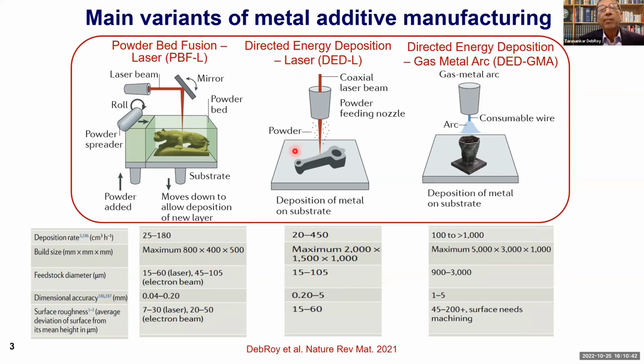We also have another technique that we call directed energy deposition using a laser beam. Here the powders are fed coaxial with the laser beam, and a computer guides the passage of this beam and the interaction between this beam and the material. Particularly, it melts the powder while it is being deposited, as well as on the part itself. And eventually, we do many layers of deposition, very thin layers, sometimes thinner than a human hair, and we make a 3D part.